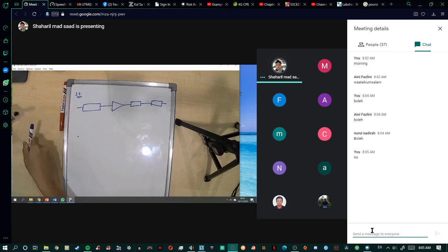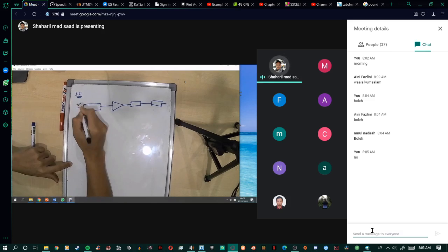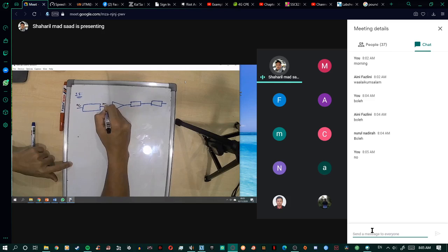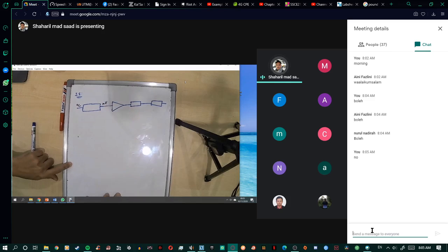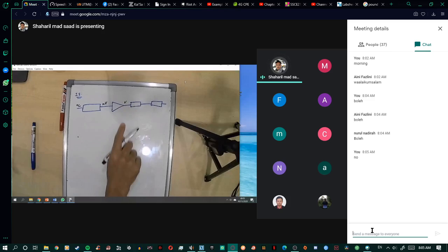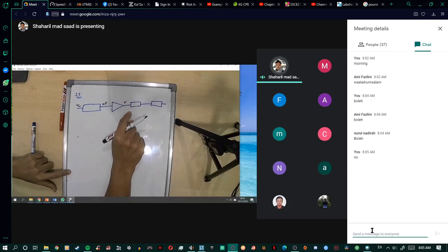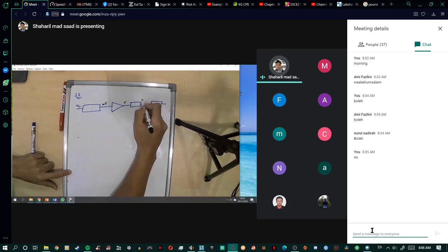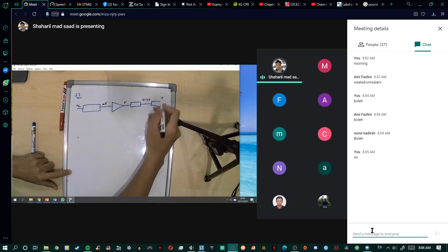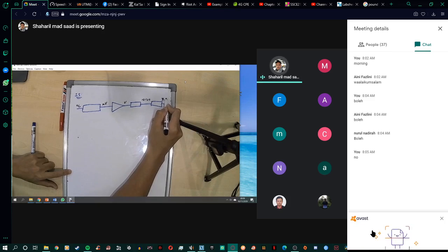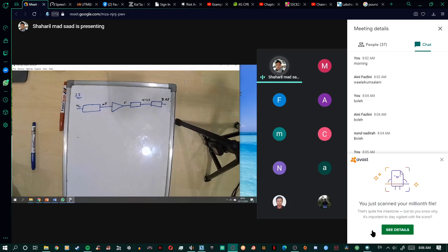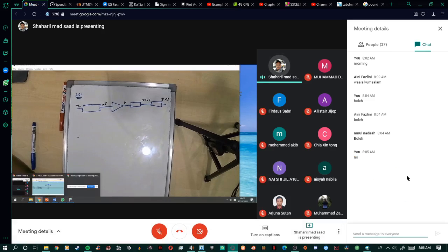For example, the input is a temperature, and the output will be in millivolts. It's too small, so you need signal conditioning to amplify it to a voltage. This is the analog voltage, which then converts to digital, maybe 101010, and displays on the LCD, for example 3.23 volts.